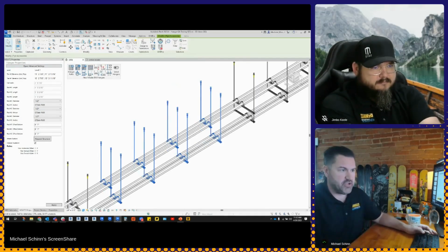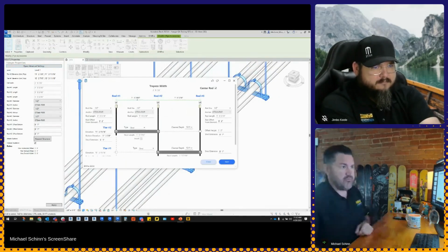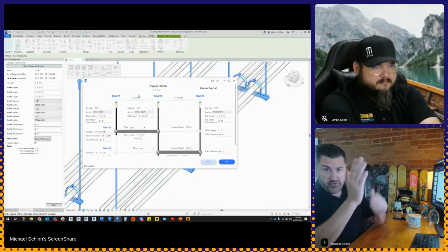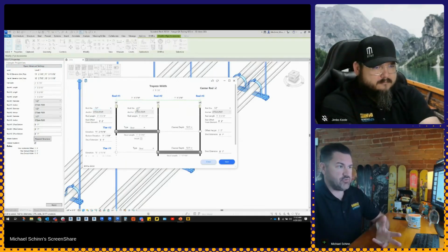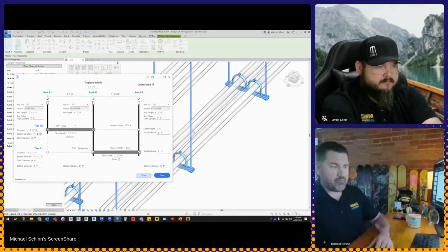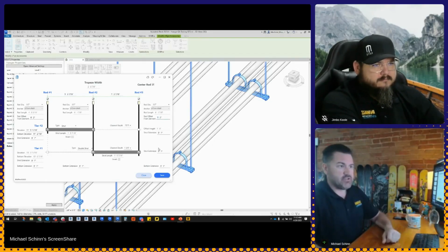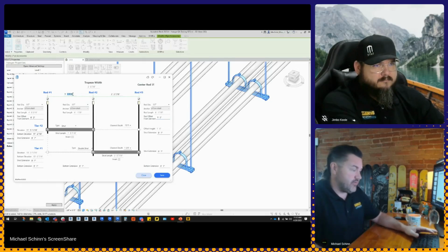Let's go into a little more detail here. Maybe we need to make a little bit more adjustments here. Click onto it. You have full control of adjusting your center rod spacing, what size rod it's working with, what strut it is. Let's maybe turn the bottom strut into a double strut or an angle iron double strut, 1 5/8. The rod offset from element. Maybe this rod here is hitting a piece of duct. I need to move that over a foot. Cool, no problem. Let's click here. Let's move that over a foot. And then let's take this and move this to 1'5".